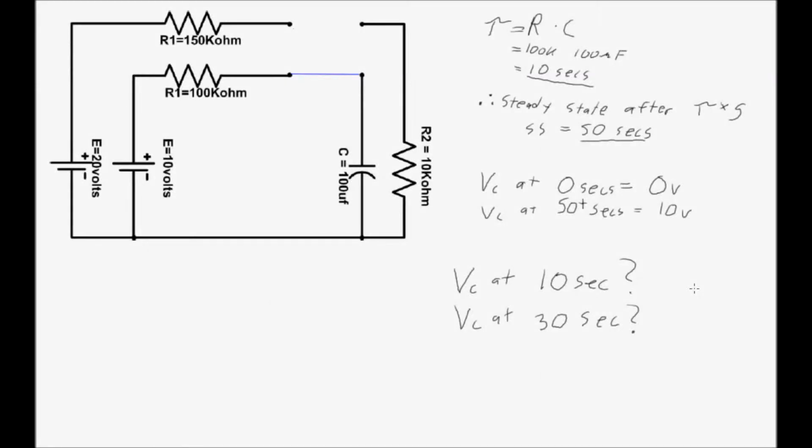Guys, this is a follow-up to the last video which looked at the behavior of capacitors in DC circuits, looking just at when the circuit is closed right at the beginning and after it's fully charged, after the 5 time constants have expired. So those are the two main. You can see at the very beginning there's no voltage across the capacitor. At the very end, at the end of the 5 time constants, it's a full voltage equal to the power supply. But what happens in the middle?